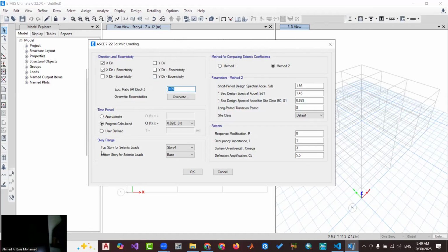For example, if we have one plane like this, and we have, for example, here column, and shear wall, for example, like this. Yeah. And here in the middle, we have, for example, what we can say core. It's a shear wall, but complicated, or combined of many shear walls. So for this, we can make it like this to make it symmetric.